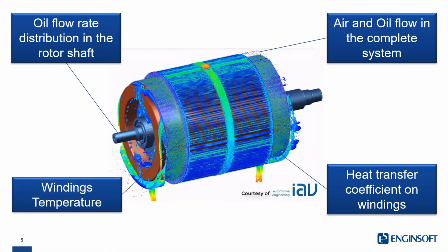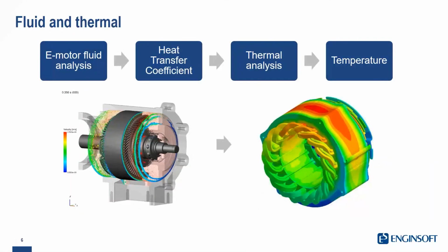And you can transfer this information, the HTC map, to FEA tools to calculate the temperature, and also predict the stress and the NVH of the system.